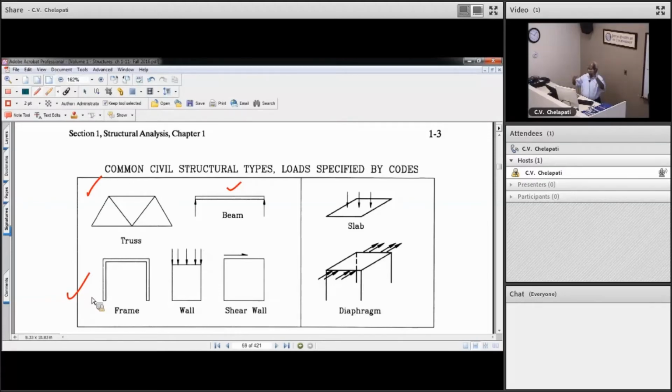In other words, a wall can resist vertical loads, that's a normal wall. But especially, the buildings carry a lot of weight on the slabs, and when the building shakes, it becomes like a horizontal force. The floors become like horizontal forces, and they come through the walls. Then we call them shear walls, because they're resisting shear. Of course, this is all civil engineering, only that much. But in real life, when you go to a 2D, this floor is a slab, right?